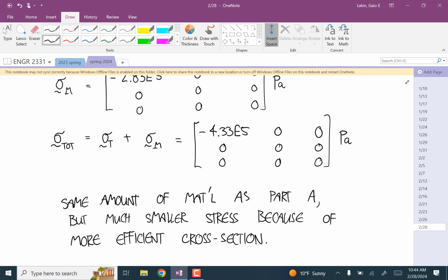I had a question. When you say at a point at the top or bottom of the cross section, for the T shape, can you pick a point on the T part of that shape or not? Mm-hmm. You can? Yeah. Okay. Yep. So you'd just have to calculate what the distance is from the neutral axis up to the top and plug that in.